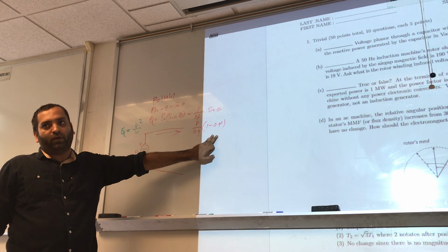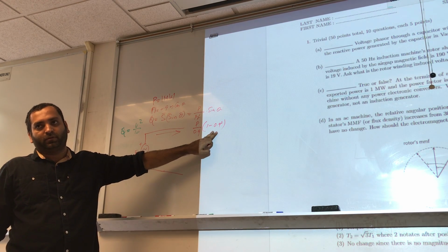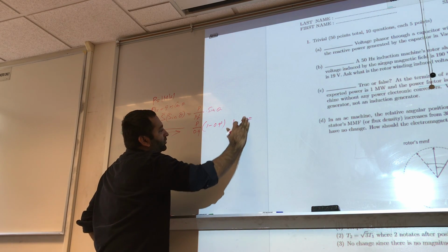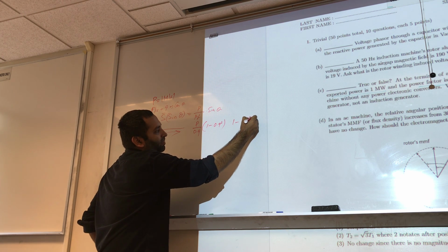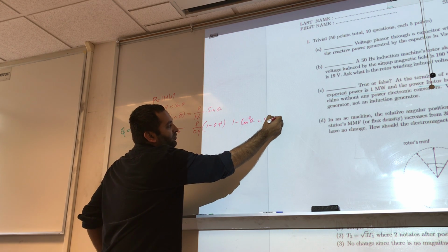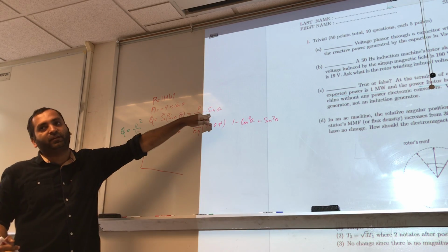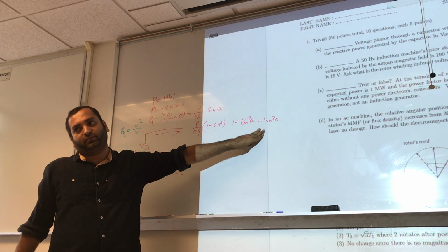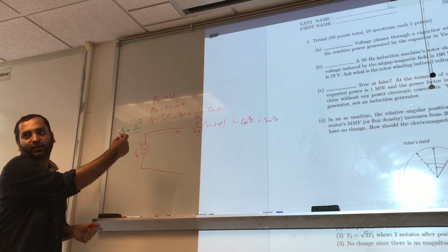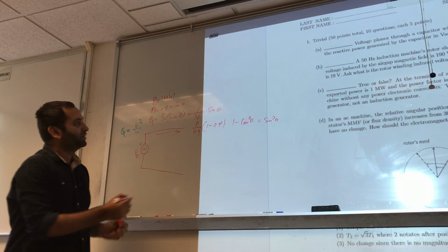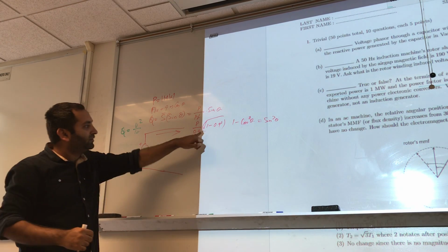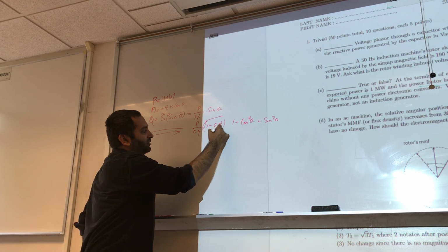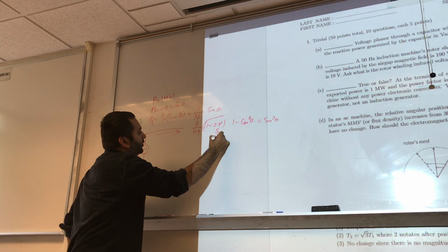You understand this part, right? Why do I do this? Because 1 minus cos squared theta is equal to sine squared theta. So I want sine theta here. I have the power factor, so you can directly use that to find the sine theta. You don't have to actually find the theta and then solve it. And square root. So what is 0.9 squared? 0.81, sorry.